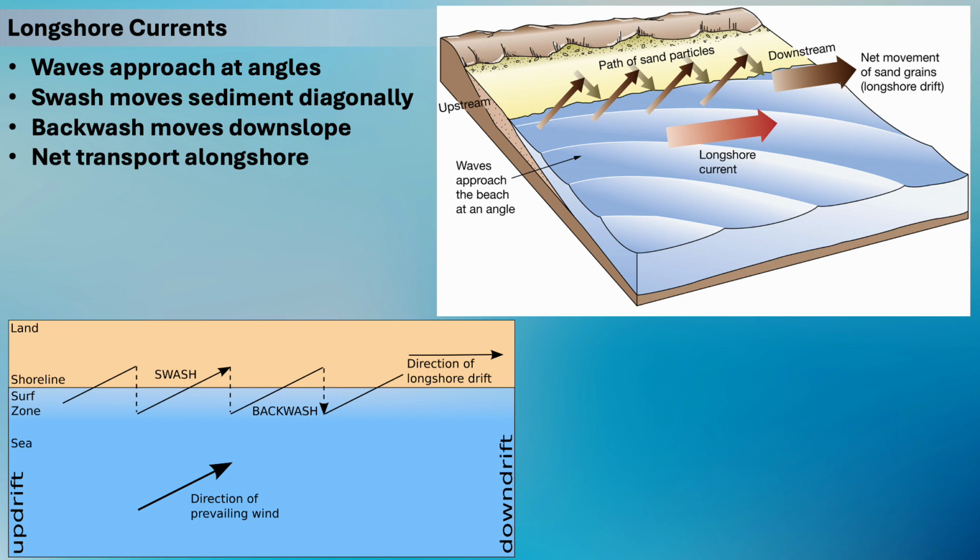Longshore transport is therefore not an isolated process. It is the direct mechanical consequence of angled wave breaking combined with gravity acting on the backwash. Over months to years, this process can move enormous quantities of sand along a coastline.